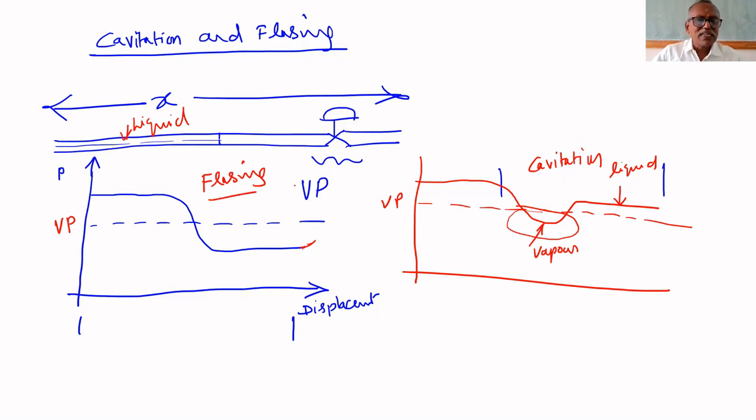But with flashing, it won't damage the valve that much, but cavitation will. That's why its name is cavitation. It will create cavities on the valve walls.